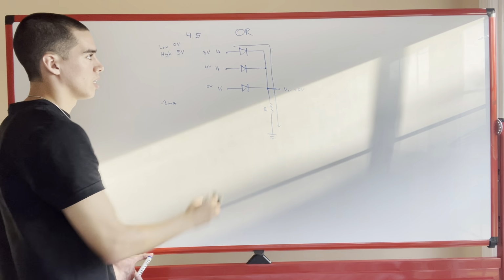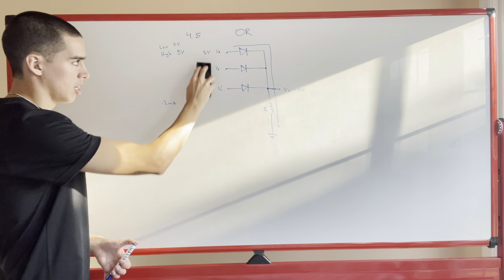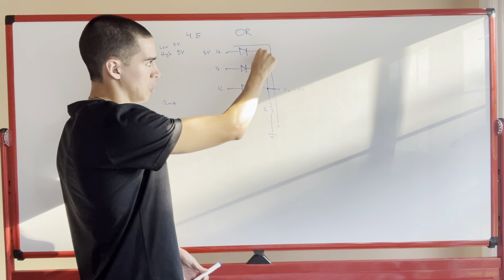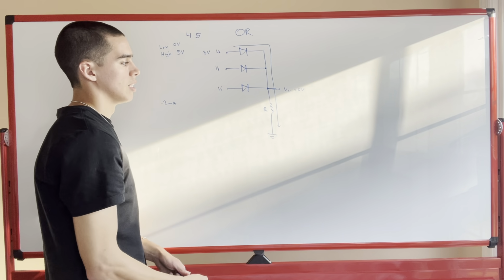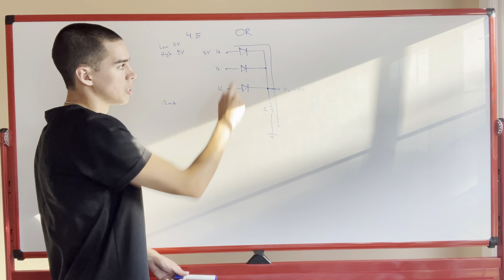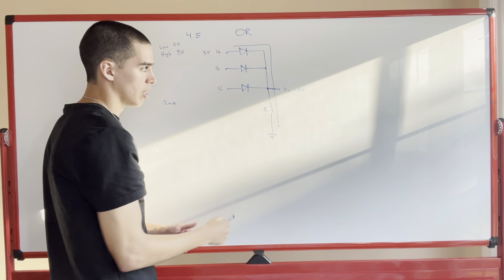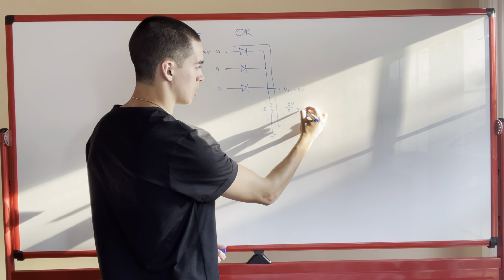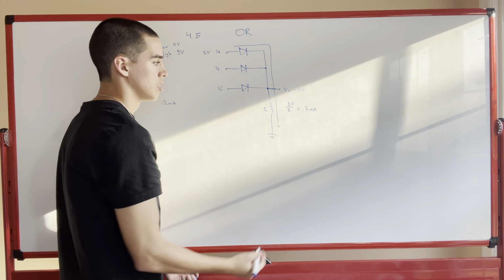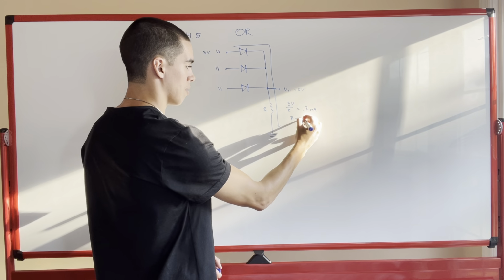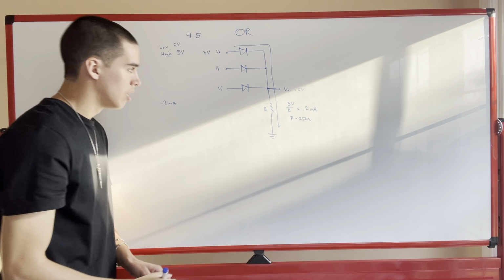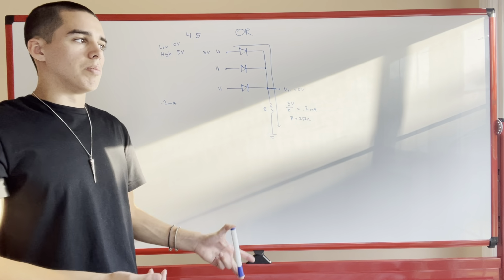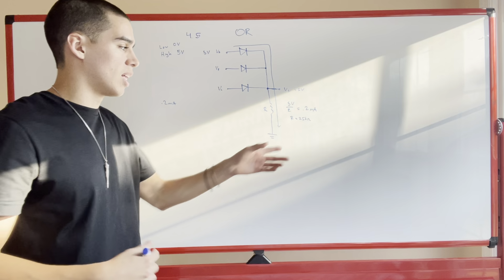We're going from here. We have one of the sources turned on. So that shorts this, so this entire node voltage is 5 volts. And so we'll have this current going through the source, 5 volts to ground over R. And we don't want that to exceed 0.2 milliamps. So we solve for R, and we get R is equal to 25 kilo ohms, right? So that sounds like the answer we want.